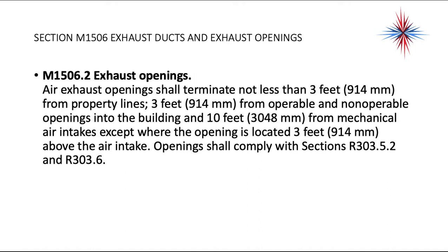Okay, so exhaust openings, we do not want to be closer than 3 feet from the property line. Again, we need to keep the grease and smells and odors and smoke coming out of exhaust openings from ranges away in an appropriate manner. Okay, we also need to make sure that we don't suck the exhaust air back into the fresh air intake.